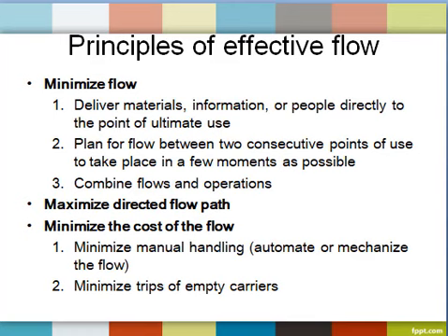For the principle of effective flow, you have to minimize the flow. Make sure you deliver the material, information, or people directly to the point of ultimate use. Plan for flow between two consecutive points of use to take place in as few moments as possible. Combine flow and operations, and then maximize the directed flow path. Minimize the cost of the flow by minimizing manual handling, whether using automatic or mechanized flow, and minimize the trips of empty carriers.